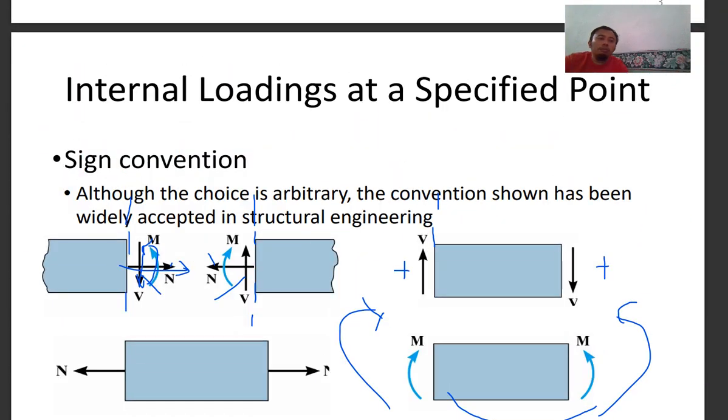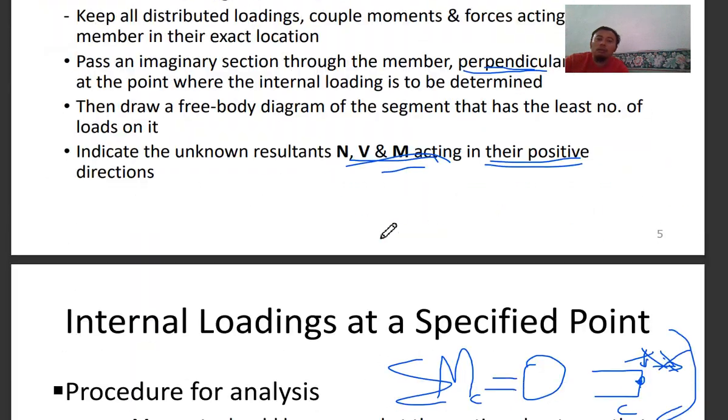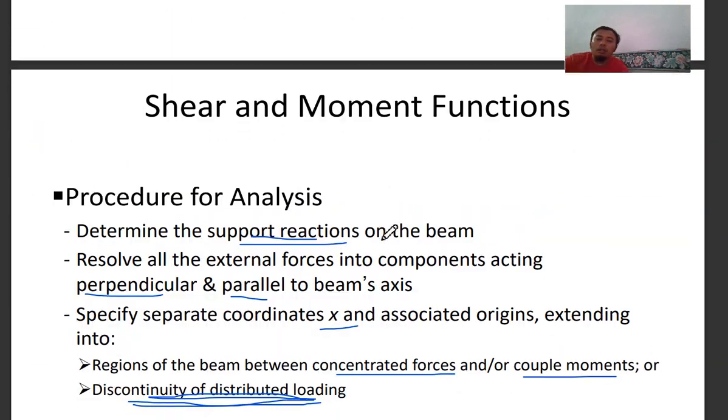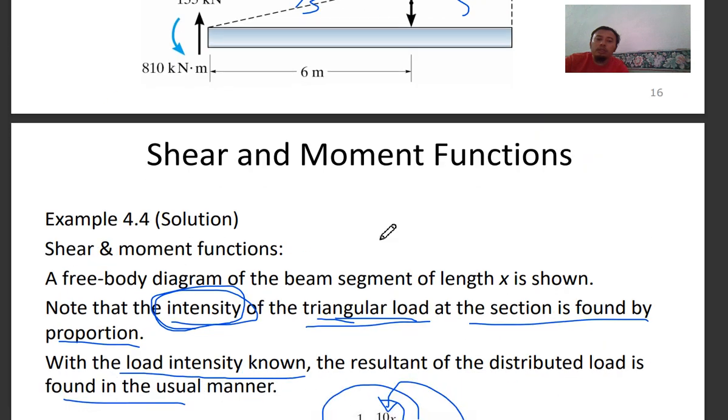Whenever you are analyzing your shear force diagram for a beam or a frame, ensure that you assume this orientation as positive. The shear will be downward positive, and counterclockwise positive. That's how you come up with this positive value of shear in this graph.